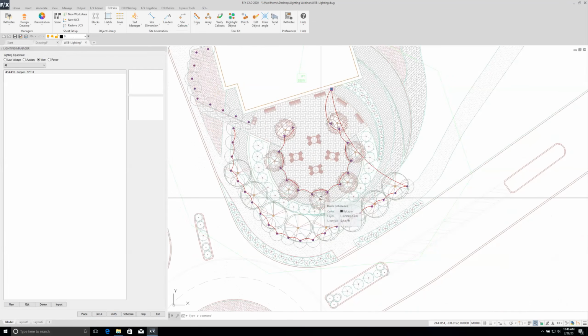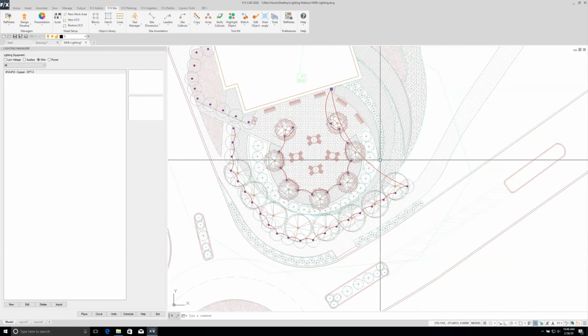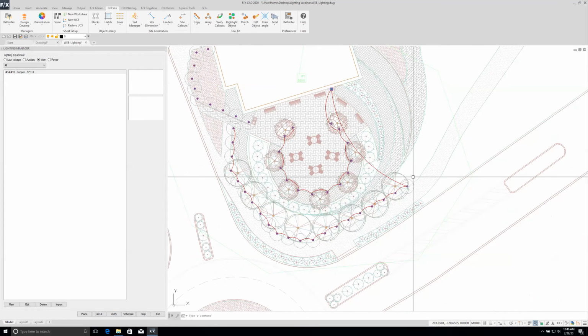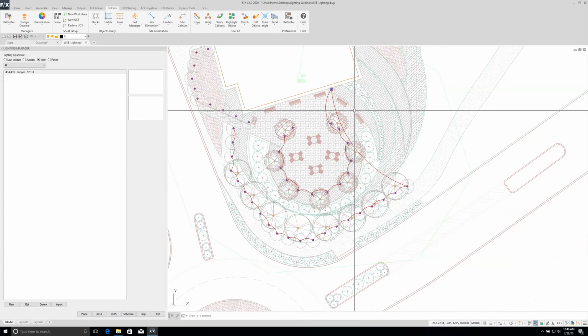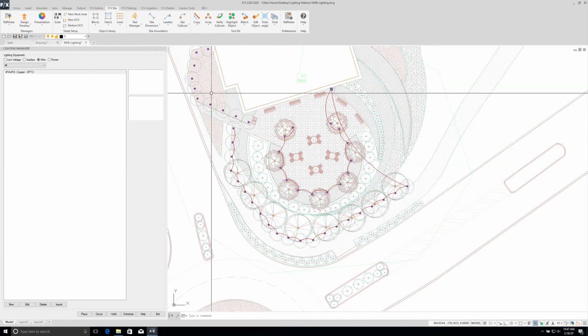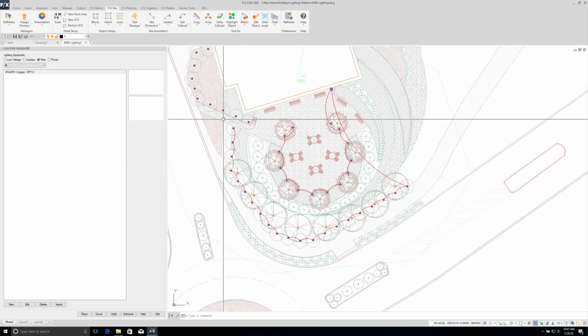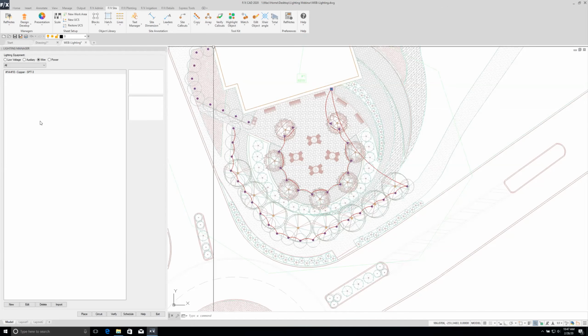And, oh, it does work. I think on my last iteration, I had wired maybe one more fixture, and it was just one past the amount that was doable for that tap. So I had to kind of reconfigure my wire. So if you do have an under voltage, you can switch to a different tap on the transformer if there's a higher one and see if that works. Or you can remove one of the lights and maybe attach it to a different run. Before I was able to attach this last light to the run on these lights, and that made the system work because it was just one light too many for the taps that were available.